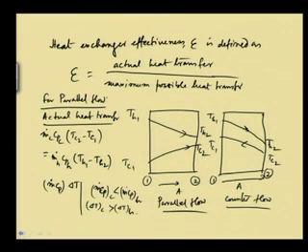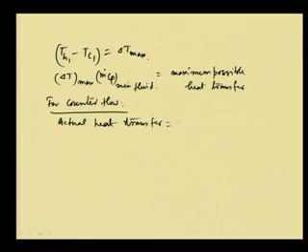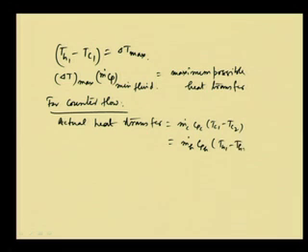It is now, for the cold fluid, m dot c Cpc into Tc1 minus Tc2, because the cold fluid is entering on the other side. Okay. Therefore, that change will be there. So, it will be m dot c Cpc into Tc1 minus Tc2. Here Tc1 is higher than Tc2, and that will be equal to m dot h Cph into Th1 minus Th2, the same thing.